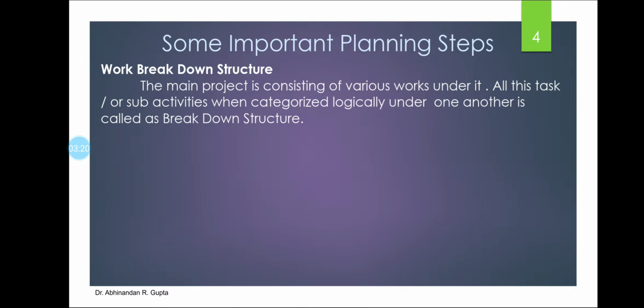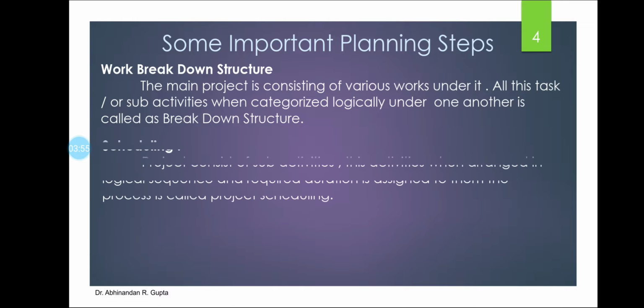This substructure work is again divided into various sub activities, right from marking, excavation, footing work, and refilling. The superstructure work is again divided into various parts: casting of columns, casting of beams, slabs, brickwork, floor finishing, finishing of the home, then the overall finishing and handover. So what we have done is divide the complete project into various sub activities. This is called the work breakdown structure for the particular project.